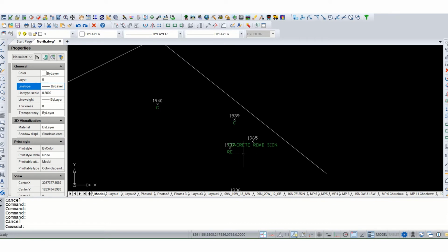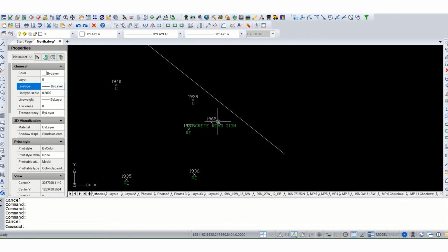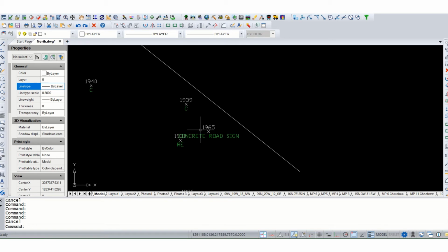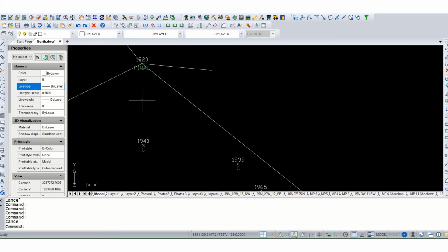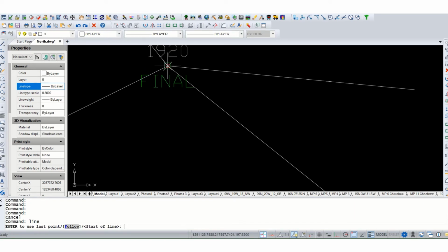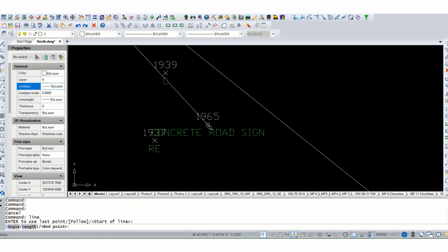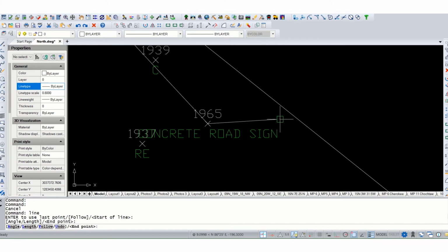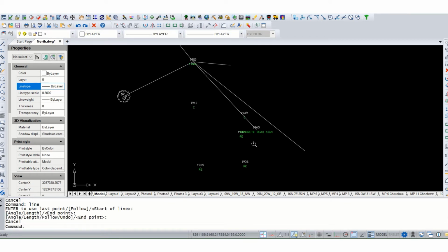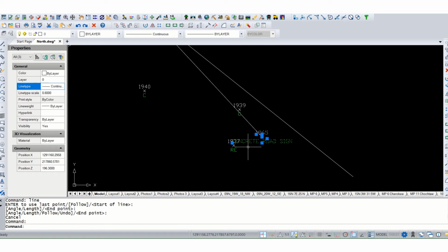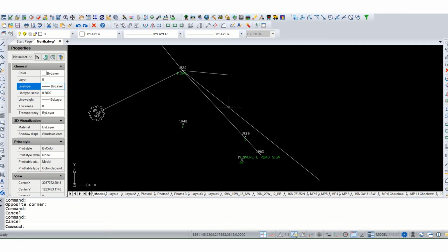I think I've got one more good shot for reference. There was an old concrete signpost, still in good condition, that makes an excellent reference. I was able to get a direct measurement on an estimated center line of that post. So I've got 1, 2, 3, 4, 5. Preferably we want 4, so 5 is one more than needed. Let's just stop there.